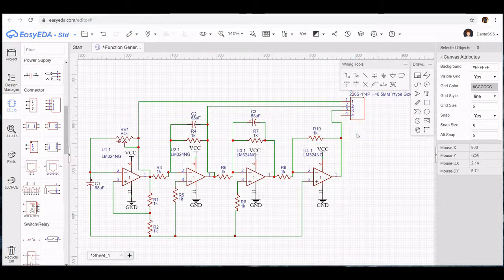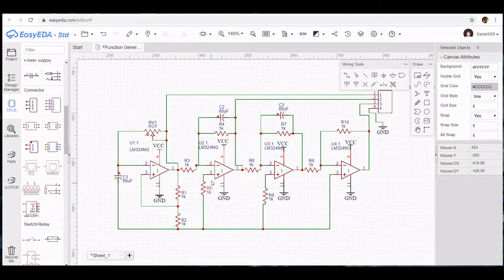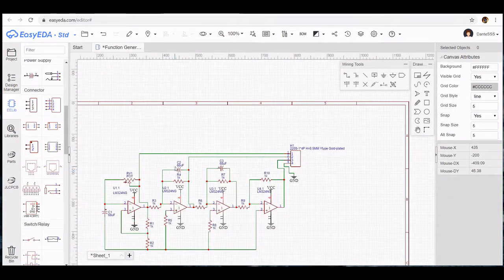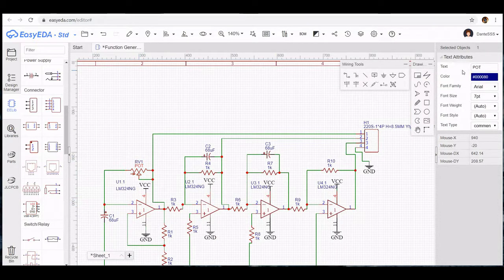Alright, so our actual third output is here. Bend the wire a bit, and we want a ground connection for our output. So just create a ground. Snake your way through the circuit, and are we done yet? I guess not, because we still haven't changed the values for these guys. So we'll just name this one 100k.